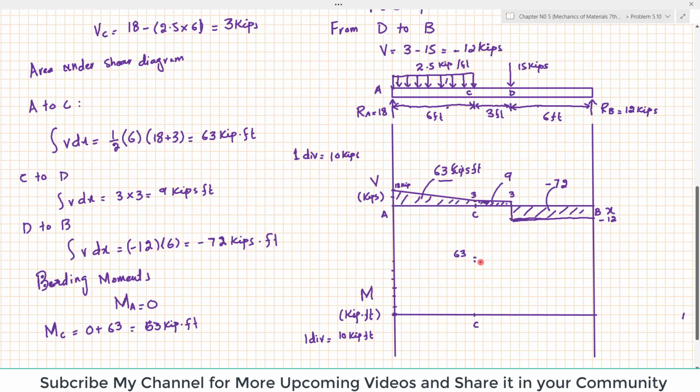Now moment at point D. So moment at point D is equal to moment at point C plus this area. So 63 plus 9, which is equal to 72 kips into feet. This is point D. So this is 60, this is 70, this is 72. So this point is 72 kips into feet.